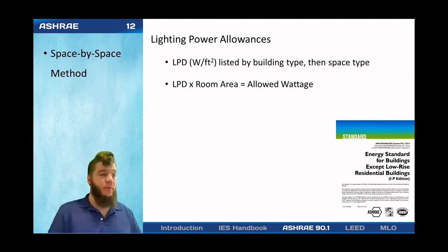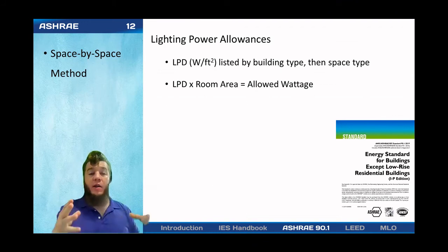And that's the number we need to comply with when we're complying with our total installed lighting power. Now, keep in mind, these are not bulb wattages. These are not necessarily even fixture wattages. They're entire luminaire wattages. So it's what wattage goes into that luminaire from your electrical system, and it's not looking at component level wattage.